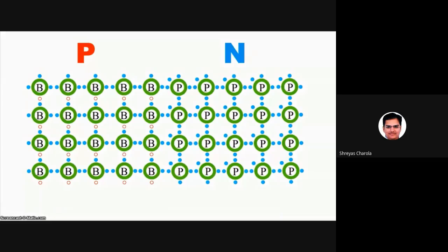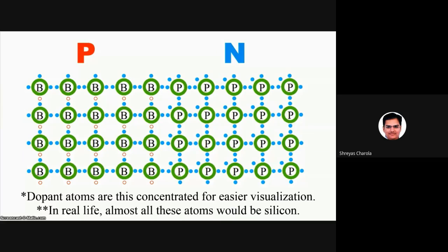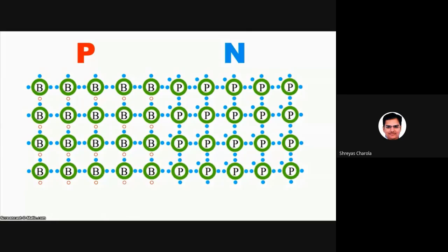Let's use the example of silicon once again, because after all, it's currently the most commonly used semiconductor material. So imagine that you have a p-type crystal doped with boron with extra positively charged holes on one side and an n-type crystal doped with phosphorus with extra negatively charged electrons on the other side. And you basically just put one by the other so that they touch. And what happens? Remember, both crystals are neutral, but they simply have freely moving negative electrons and positive holes.